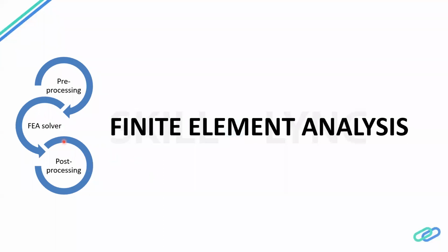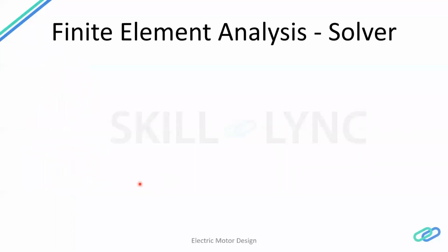And then once you have the basic results, you start post-processing them. Post-processing is organizing your results and doing analysis on them in such a fashion that you have the efficiency results, or torque versus speed at different speed locations, and all that stuff is called post-processing.